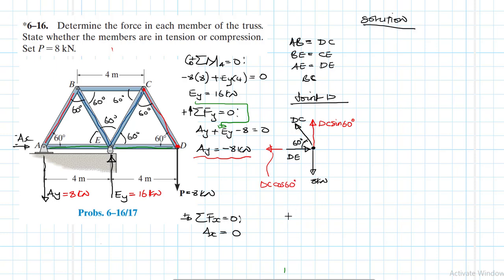All right, let's apply the equations of equilibrium. Let me delineate the boundary here. I'll start with the summation of forces in the y direction, because we only have one unknown there. Summation of forces in the y direction, going up being our reference positive.